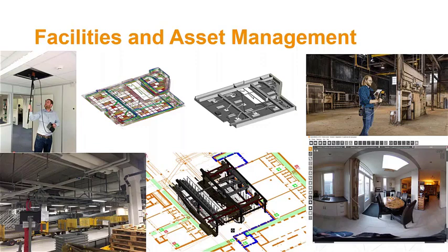But one really useful way to use our technology in the realm of facilities and asset management is above ceiling scanning. Most buildings these days have acoustic ceiling tiles, and it's really quite difficult to map or to survey assets in a ceiling plenum using traditional methods. You'll spend a lot of time with your head above the ceiling. You can also do this type of mapping with terrestrial static scanners. However, it's a much more time-consuming and invasive process to do that.